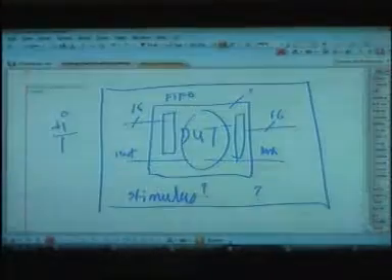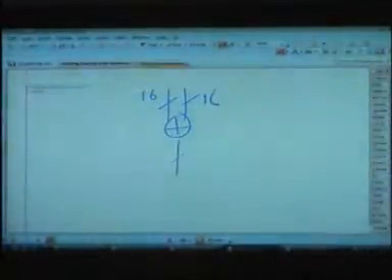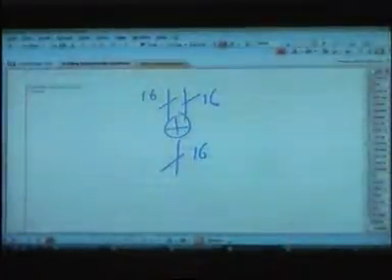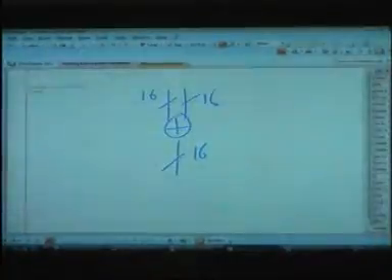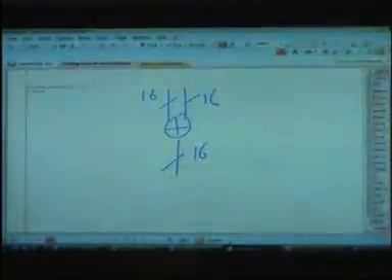And just to expose the challenge, for example, I ask you to make a simple 16-bit adder yourself. Now you design an adder, and you test it for 100 values, for example. You say, oh, I have given 100 test vectors, it's working on 100 test vectors, it means it's working. No, it's not working.